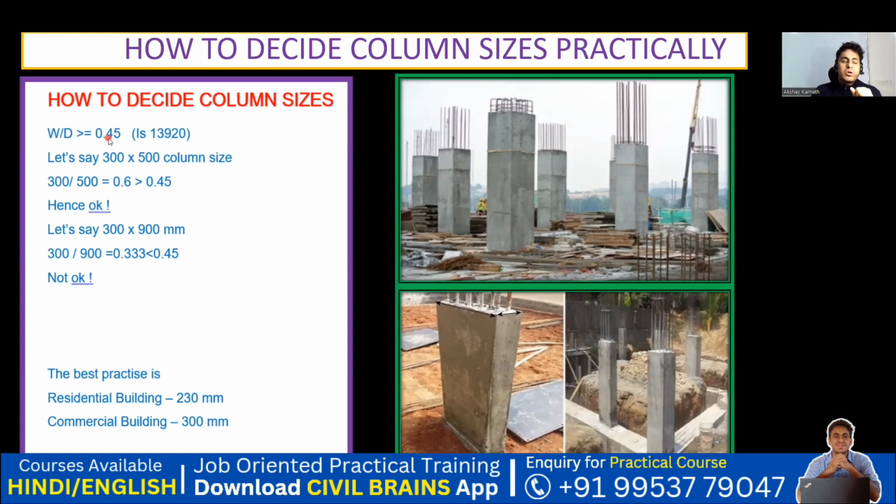If it is greater or equal to 0.45, only then we should go with this particular size of a column. So now let us say what is width. Width is 300 and depth is 500. Try to do the calculation. 300 by 500, I'm getting 0.6, and 0.6 is greater or equal to 0.45, obviously. So I can go with this dimension of 300 by 500.